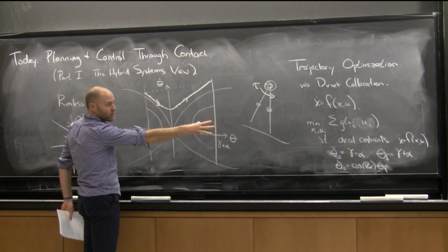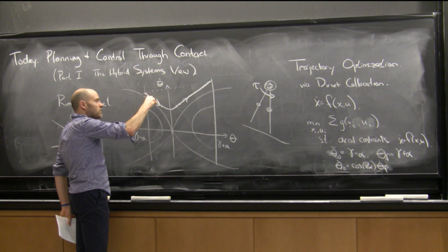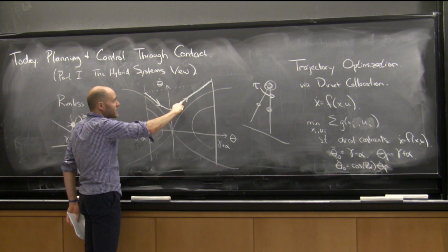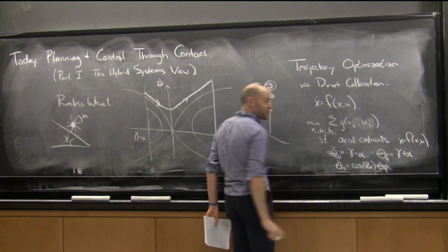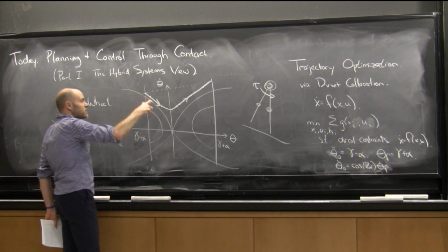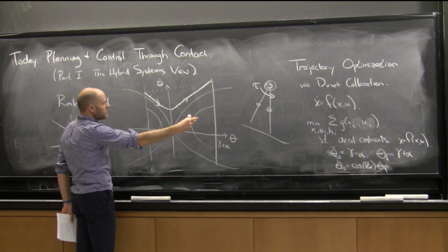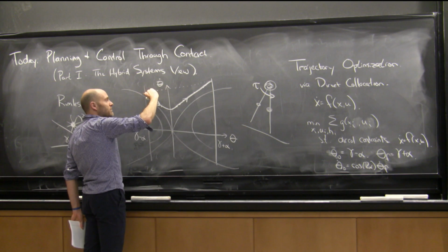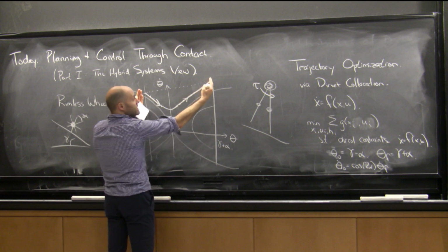I've often, when I've written this, implied that these knot points were somehow some fixed time step apart, right? But in fact, the way I implemented it in the code, I might have even forgotten to say it before, is I actually had the time intervals in as decision variables. You call it dt or h. These decision variables need not be fixed in time. They can spread out over time. So if the duration of this trajectory is not known, that's okay.